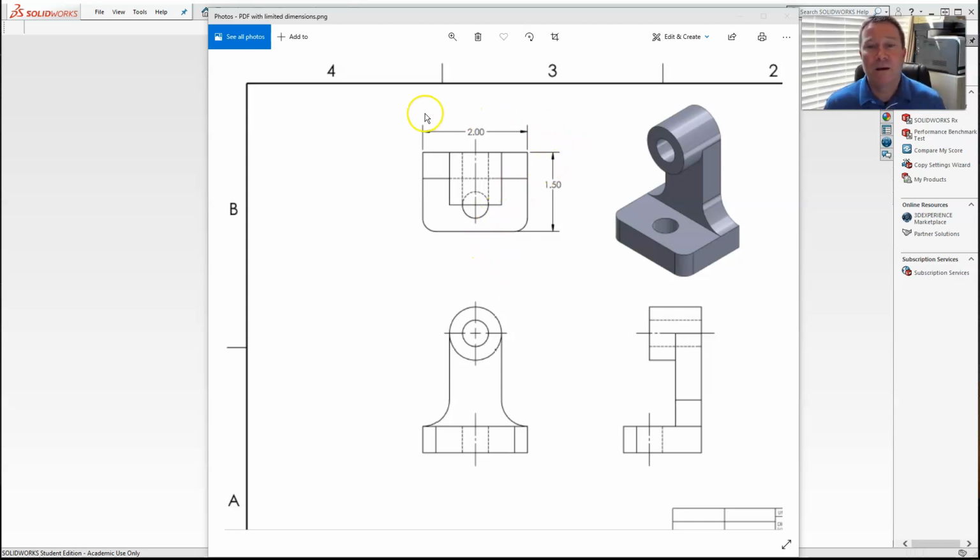So let's look at our three views. In the previous example, we chose the corner. In this example, I'm going to choose the center because of the symmetry. Reason being, if I choose the center as the origin of the part in the very back, the center of the front would be down here and the center of the right side would be down here. That would place the top image and the front image lined up right on the back side of it, and then the right view would actually be right down the center.